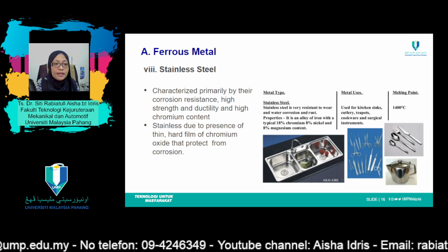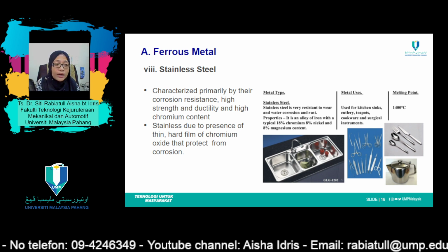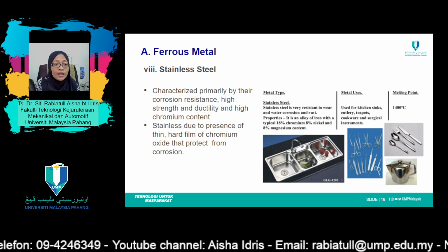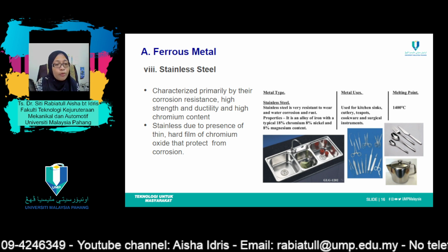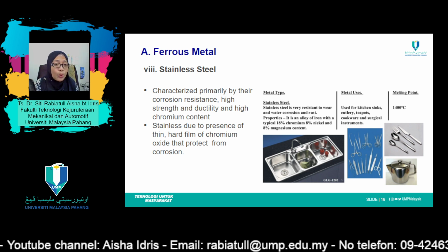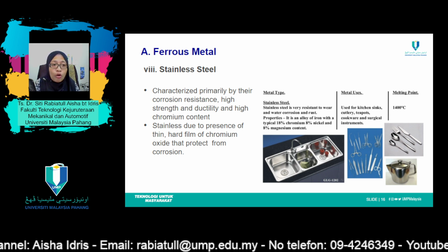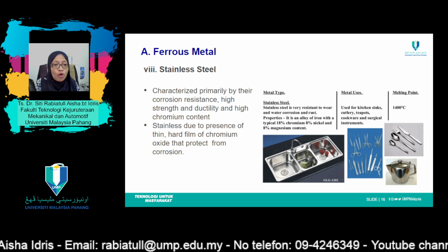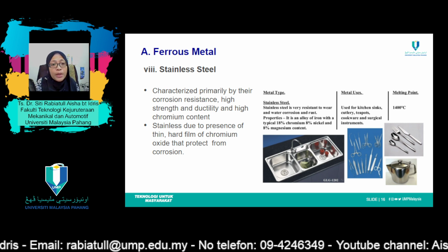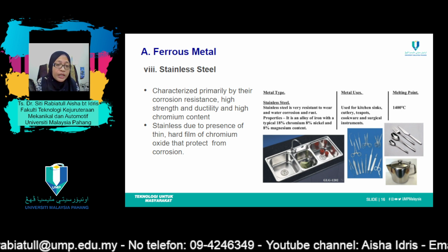Stainless steels are highly resistant to corrosion in a variety of environments, especially the ambient atmosphere. Their predominant alloying element is chromium. A concentration of at least 11% chromium is required. Corrosion resistance may also be enhanced by nickel and molybdenum additions.